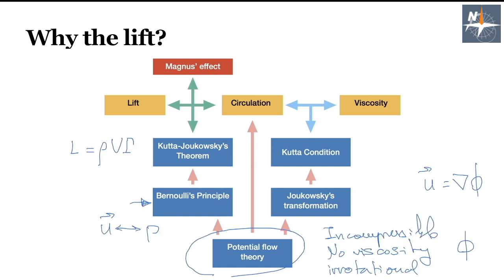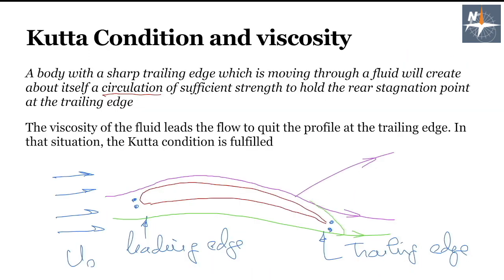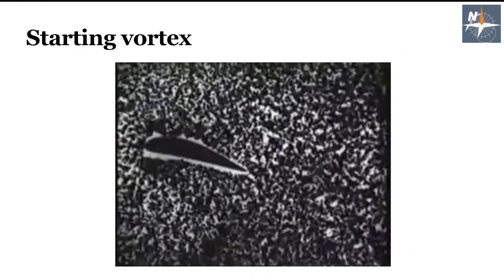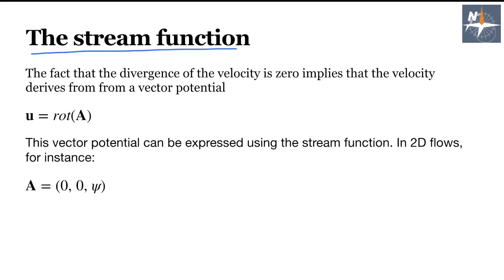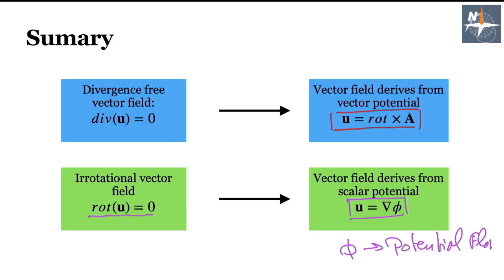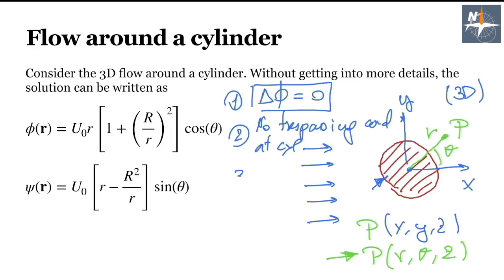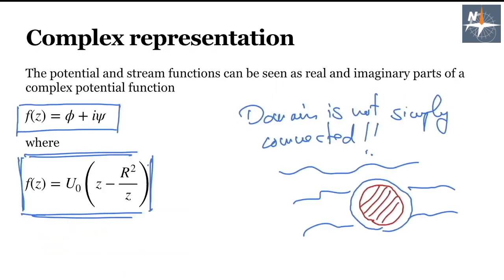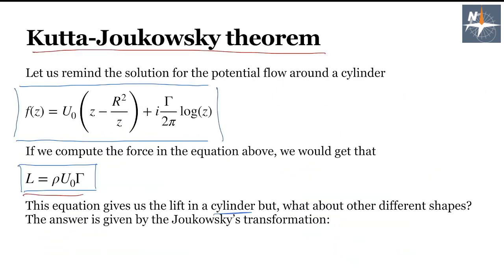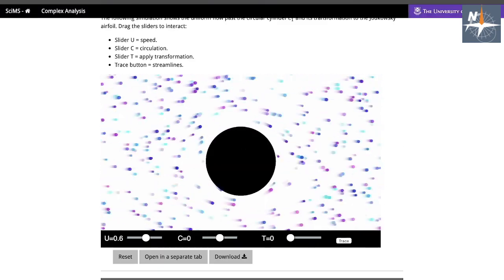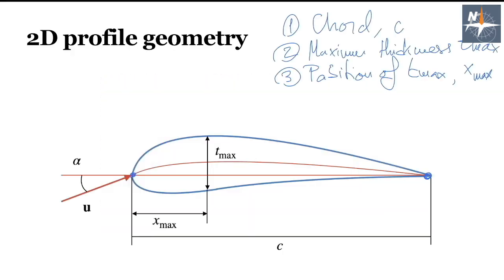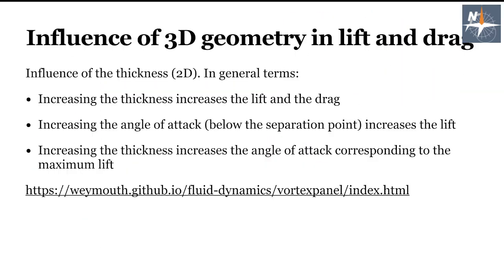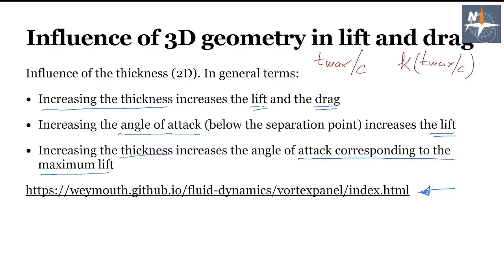We have gone through the physics of the problem, focusing on the importance of the viscosity to explain these phenomena. Also, we have studied some general aspects of the potential flow theory, which, although it does not consider viscosity, allows us to calculate lift forces in hydrodynamic profiles using the circulation and linking it with the lift force through the Kutta-Joukowski theorem. Prior to performing simulations, we have also revisited the geometrical definition of profiles, as well as studied the three-dimensional effects that happen in this type of hydrodynamic appendages, such as the induced drag.